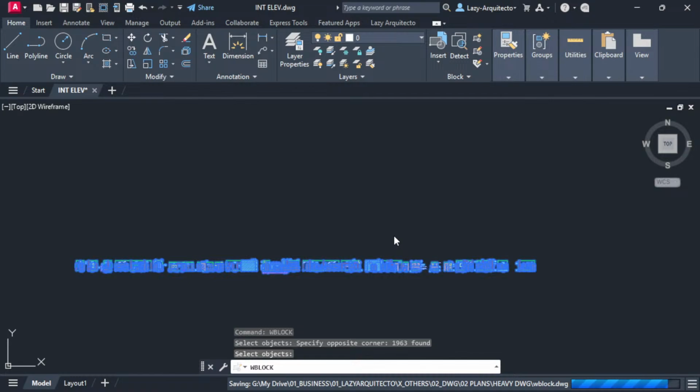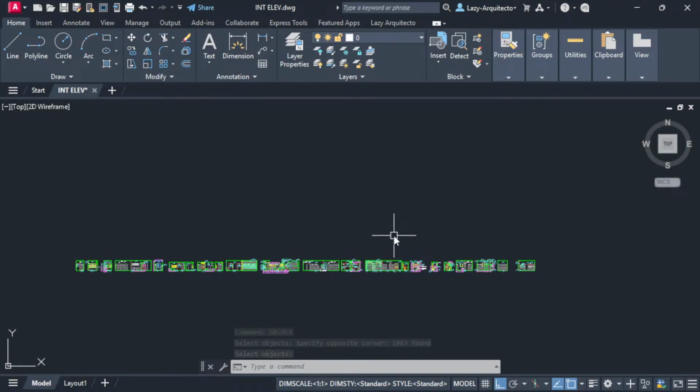And when they share their files, they exported it as a DWG CAD drawing, but they might contain all sorts of things and objects that don't work in AutoCAD, such as proxy objects. We're gonna talk about that later. We're gonna try a method for proxy objects.